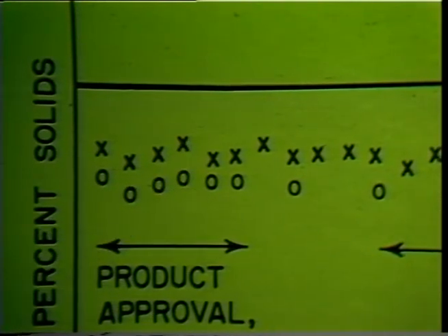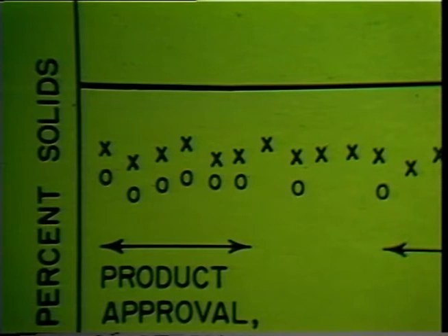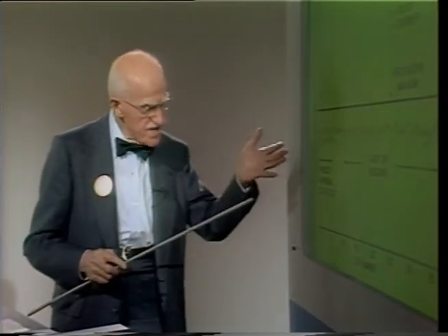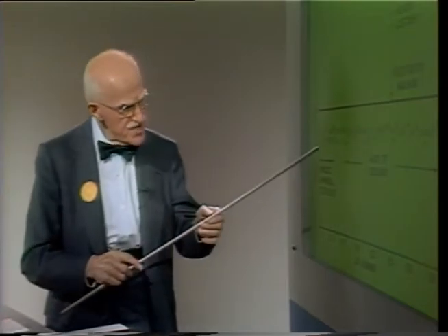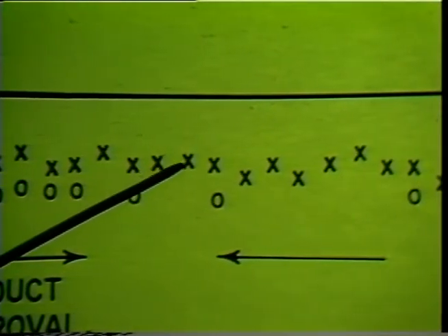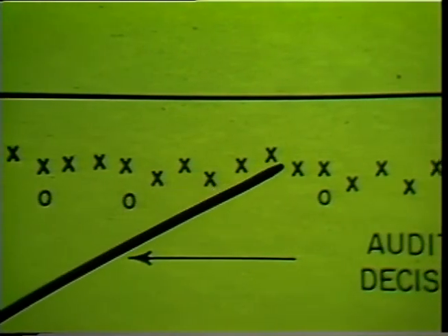The first 6 shipments show that the vendor delivered product which conformed to specification. Second, that the vendor's laboratory made correct decisions. And third, that the test methods differ, but the vendor's test is more strict. Now the buyer reduces testing and relies increasingly on the vendor's test laboratory.